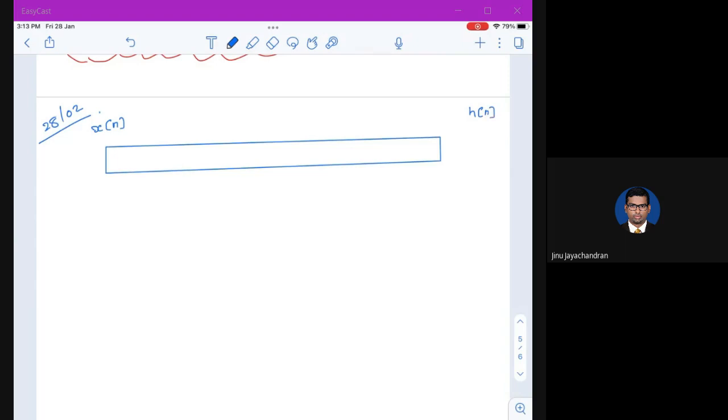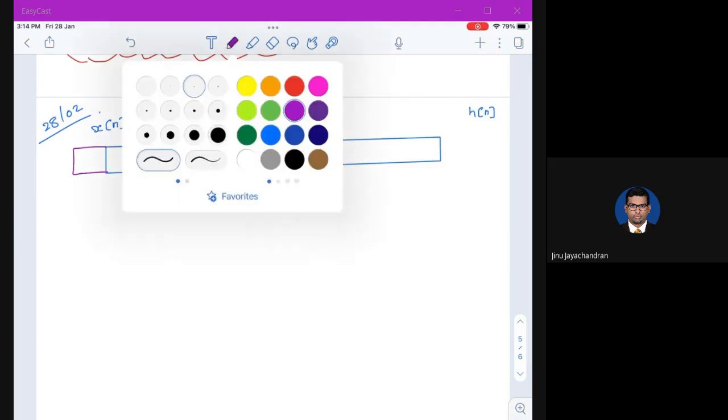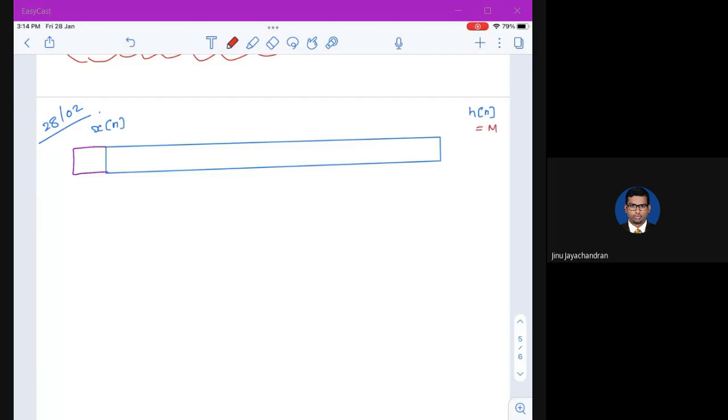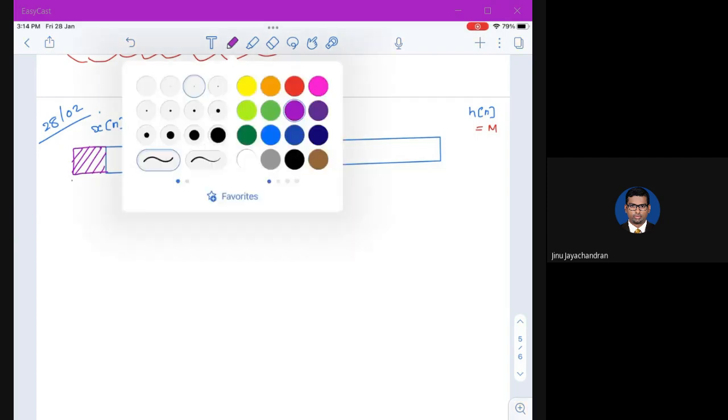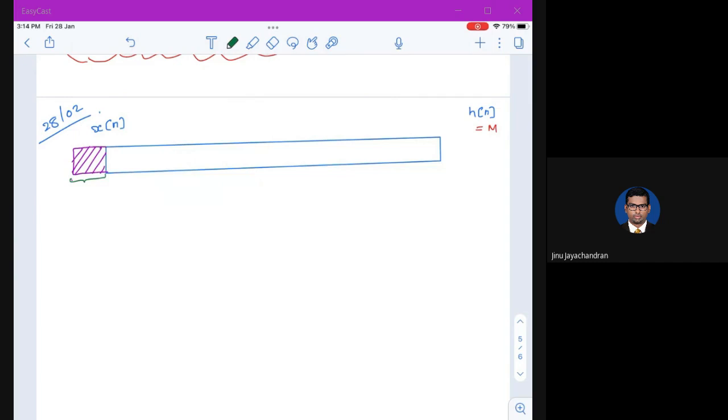So what we did in the overlap save method is as follows. First, initially you append m-1 zeros to the data block. Remember, the length of h of n is equal to m. M is the length of the filter or the system that you are going to use to pass this input data. In that system, you first append x of n with m-1 zeros. So x of n is this huge, very lengthy data block.